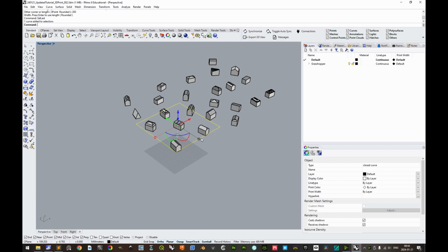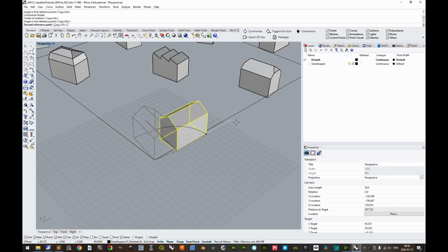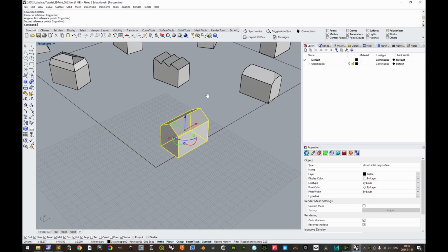But if they cannot easily fit, then the following procedure might be recommended to maximize the effective usage of the workbed area. To maximize the effective usage, one might first rotate all objects so that they are as orthographically oriented as possible. Do this by selecting the first object, type and enter rotate, choose a suitable starting point, the vertical axis of which the object will rotate around, make sure ortho and O-snap are both active, select a suitable end point, and choose, by left-clicking, the intended orientation of the object. Repeat this for the remaining objects.